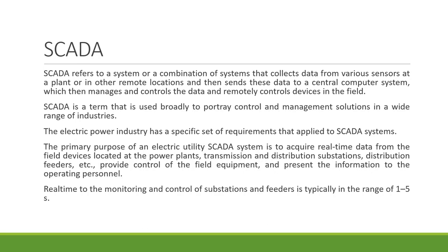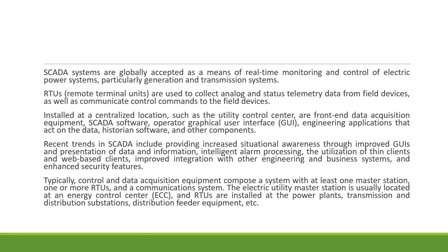So the real-time monitoring and control of substation and feeders, if you think about the time, it is only 1 to 5 seconds. Just think about that. I said 1 to 5 seconds, it's over. So that monitoring and control could be achieved with the help of SCADA. SCADA is accepted globally for monitoring and control of electric power system on a real-time basis, particularly at generation and transmission system.